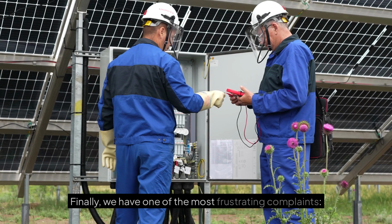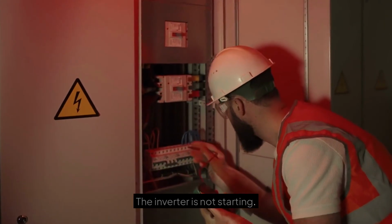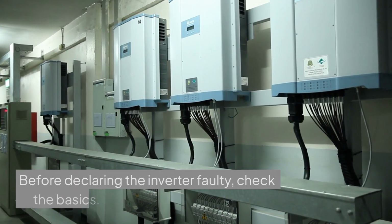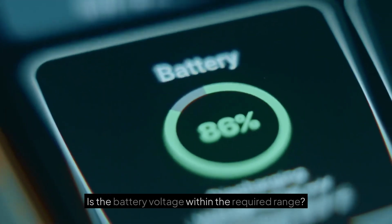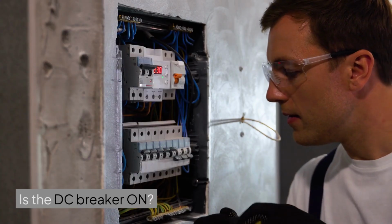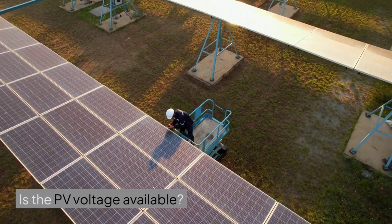10. Inverter not starting. Finally, we have one of the most frustrating complaints. The inverter is not starting. Before declaring the inverter faulty, check the basics. Is the battery voltage within the required range? Is the DC breaker on? Is the PV voltage available?